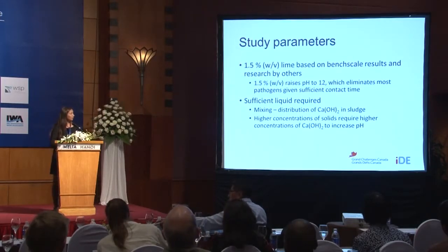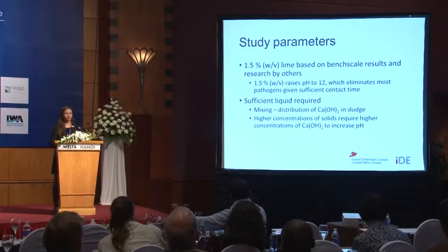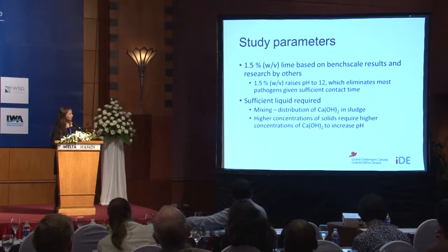This was enough to raise the pH to 12, which eliminates most pathogens given a sufficient contact time. For bacterial viruses, this is on the order of hours, and for something like Ascaris eggs, it's on the order of a week or two. This has also been shown by a few other groups.